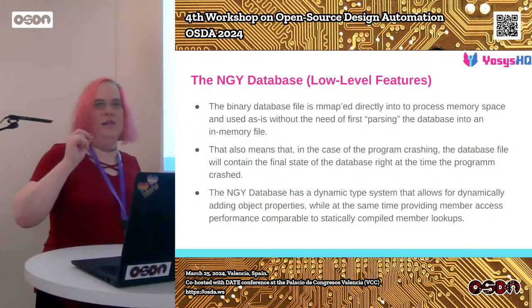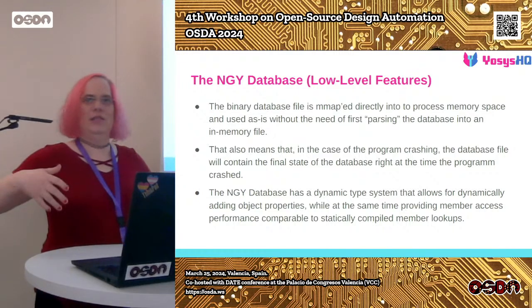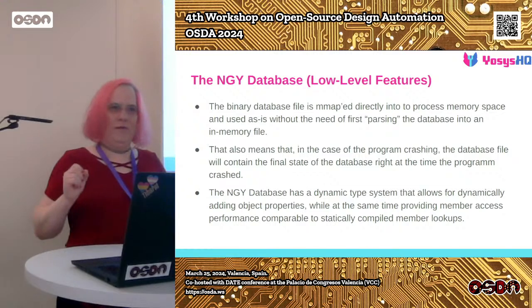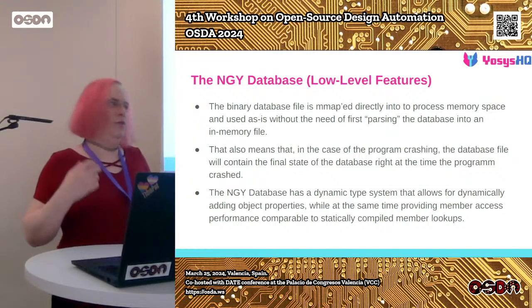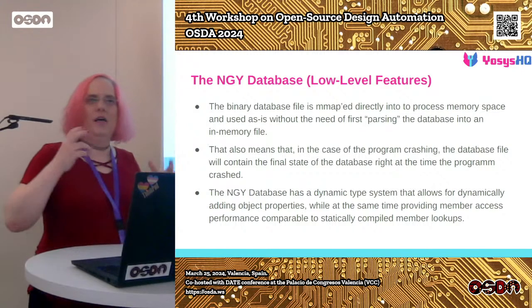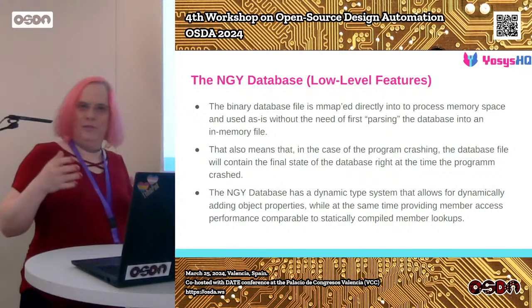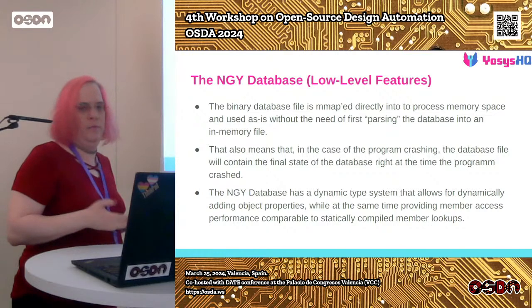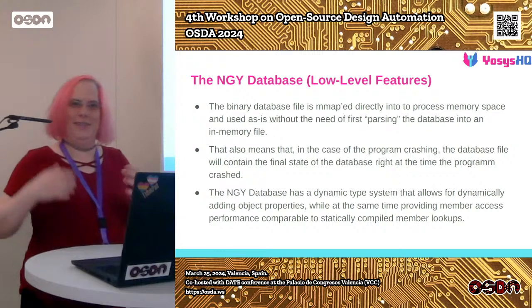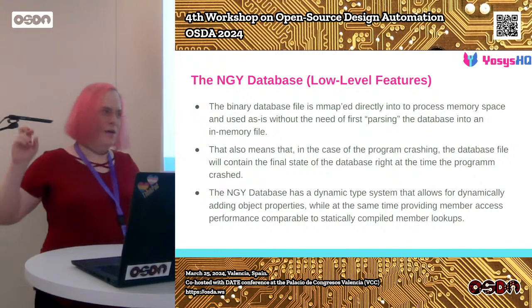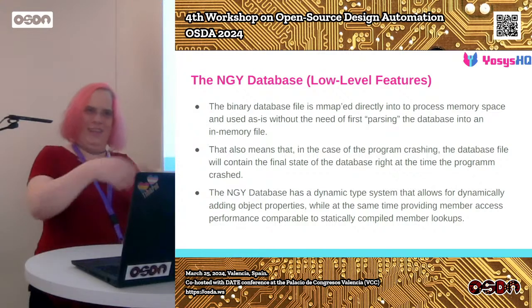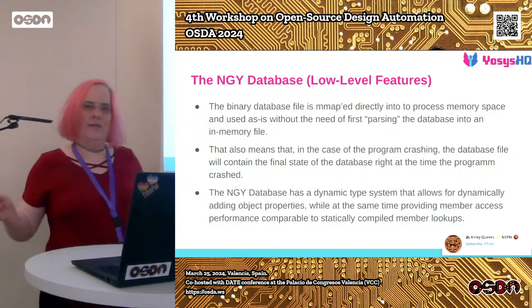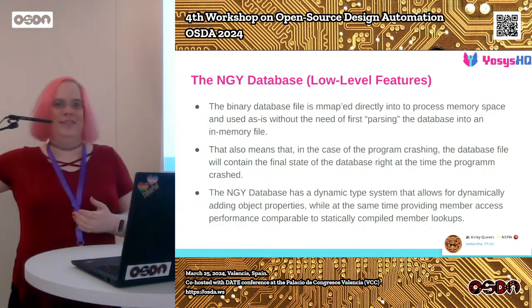So for any pass or any design that is stored to disk, we can just run an executable and be able to extract the value or whatever from the design with almost the same speed as if you would ask it with a Tcl command or something in another tool. That solves a couple of different problems. One of the problems that I'm hoping this will fix: they say we can't give you the input design, something like this. We can only try to create a checkpoint at the end, and then you can get that netlist out. That's slightly different from writing out the RTLIL text file and reading it back into a new project, where you don't hit the same bug anymore.